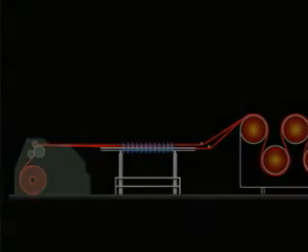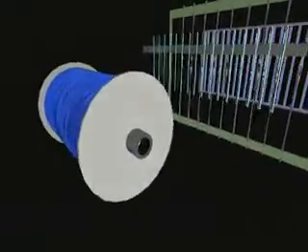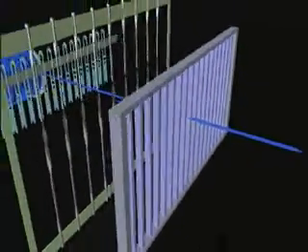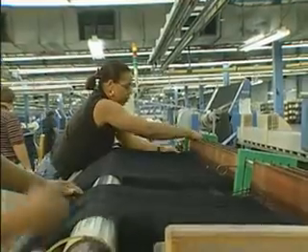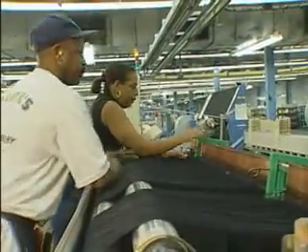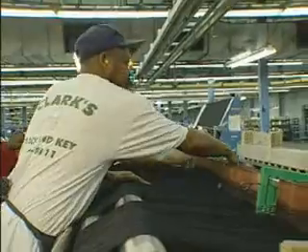After sizing, the warp ends must be placed through the proper devices for weaving in the correct order for the desired design and color pattern. This process is called drawing in, where each warp end on the loom beam is pulled or drawn through a drop wire, a heddle that is in a harness, and then finally through a dent in a reed. This is one of the most important steps in weaving, since an incorrect color or weaving pattern will result in second-quality cloth.